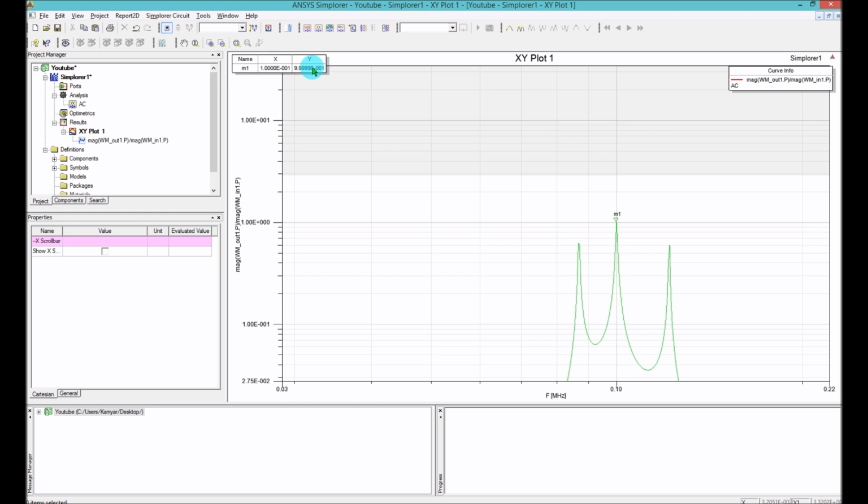If the quality factor of the coils is poor, then you would not get that much efficiency, and also we are measuring it purely with no other parasitic components around. So if you're actually designing that, you will not get exactly 99.99%. You may get a lower amount, but it's kind of surprising for me that the result is that good.